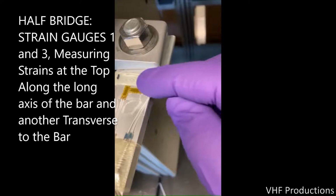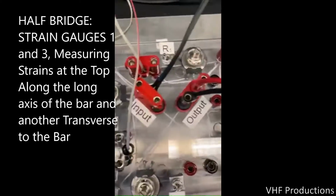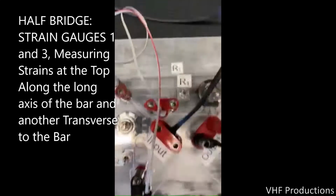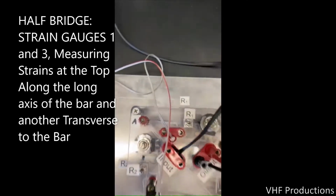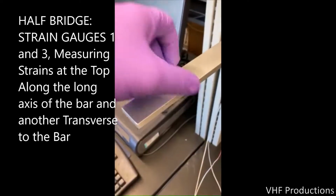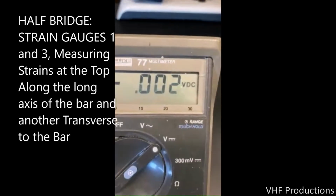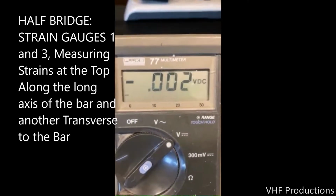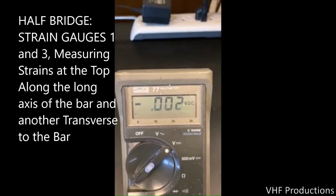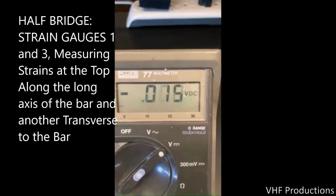However, since we're bending the bar by pressing down at the end so that it bends in its most flexible condition, the transverse strain gauge, which is measuring strain across the width of the bar, will have no strain occur. So that strain gauge doesn't see a change in resistance, even though we have two strain gauges input into the circuit. The one longitudinal one on the top is seeing all the resistance change, whereas the transverse gauge sees no resistance change at all.